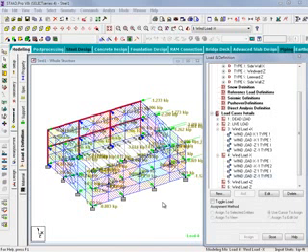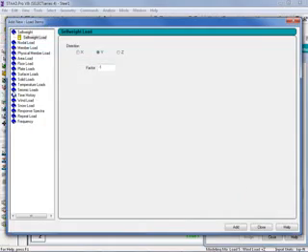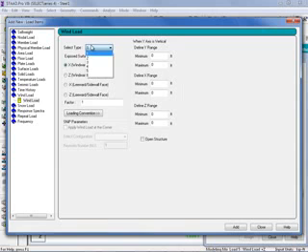To complete this process, we will also generate wind load in our positive and negative Z global axis direction. And we can see that load types 4, 5, and 6 are appropriate and have the correct parameters for the global Z direction. Here for our windward face, we will select load type 4 and select the Z windward face.